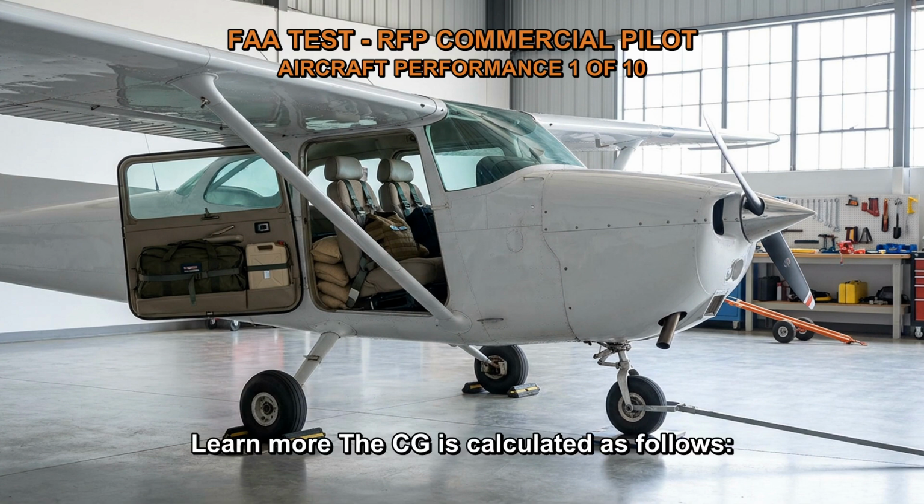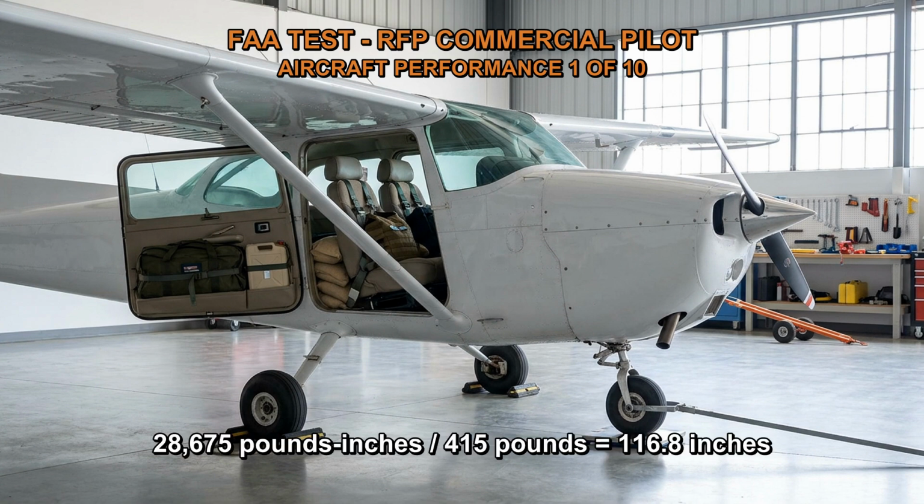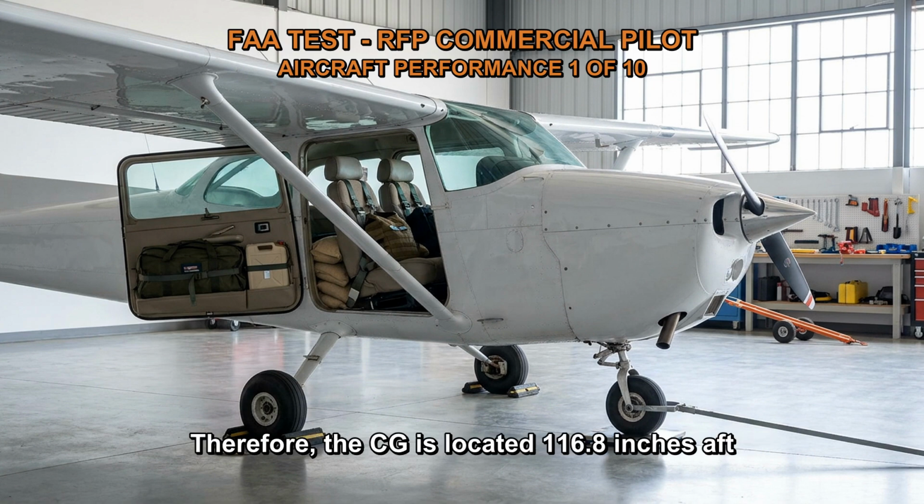The CG is calculated as follows. CG equals total moment divided by total weight equals 28,675 pound-inches divided by 415 pounds equals 116.8 inches. Therefore, the CG is located 116.8 inches aft of the datum.